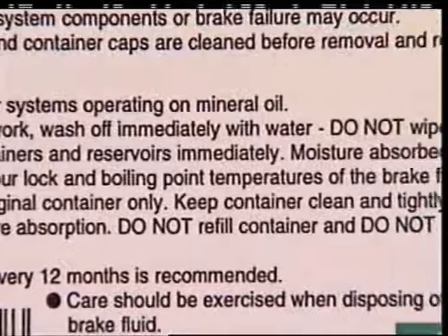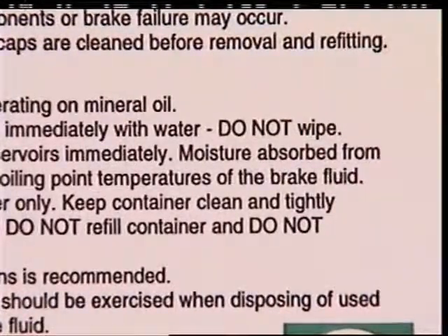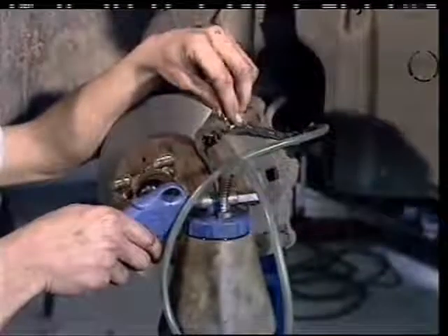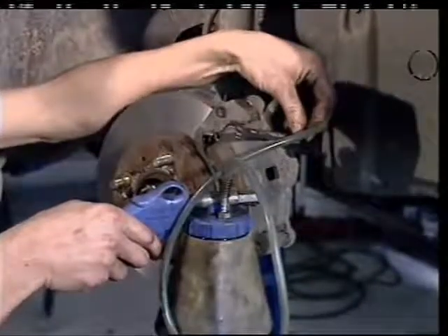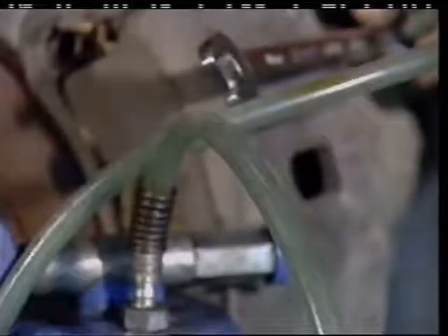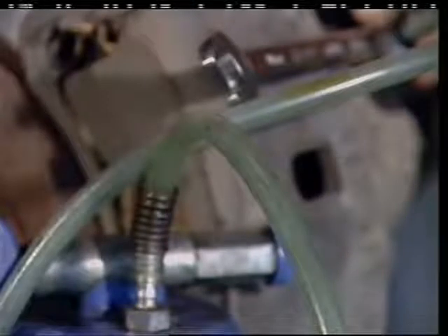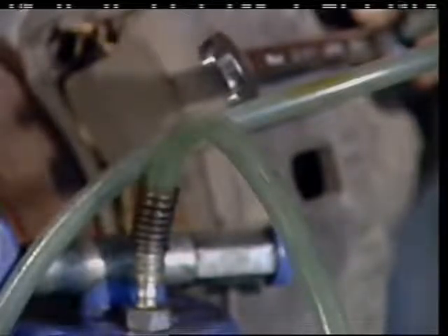This is important because as moisture is absorbed, it lowers the boiling point of the fluid. Brake fluid should not be mixed with mineral-based oils or solvents. If contamination is suspected, the braking system must be drained and flushed with a suitable solvent and rubber components replaced.